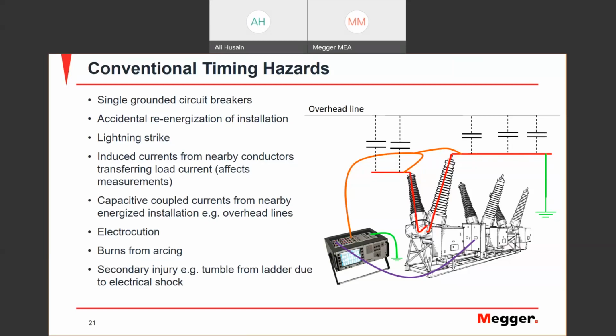And actually, we got some test equipment, some circuit breaker analyzers, sent to the factory for repair because the channels in them got burned because of these leakages coming in. If, let's say, you are testing a 220 kV line and you get 1 or 2% leakage, that's like 2 or 3 kV, which is very dangerous.